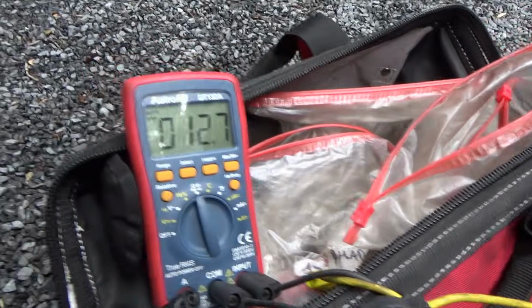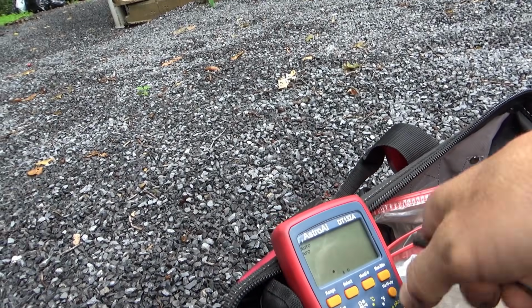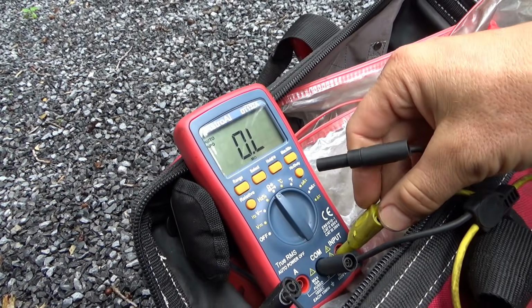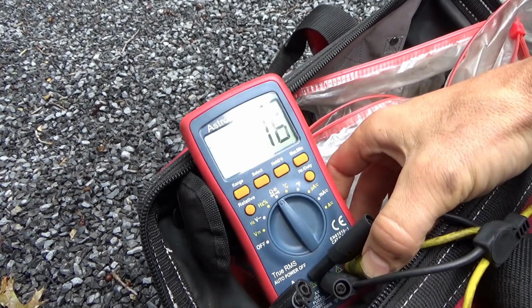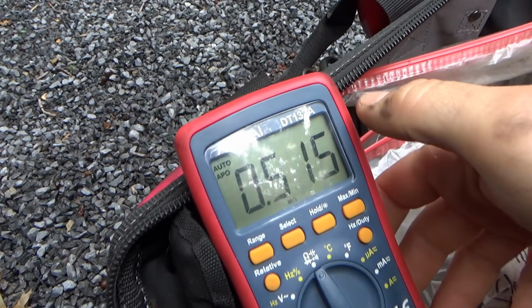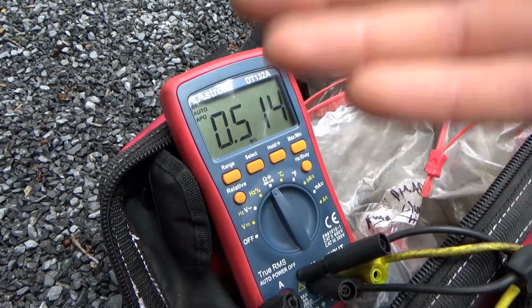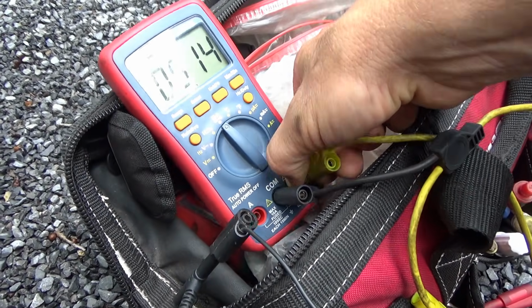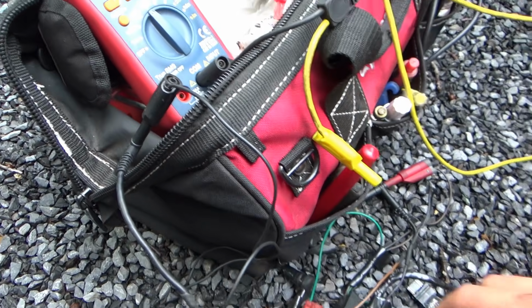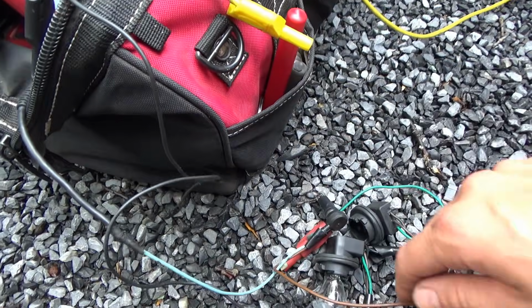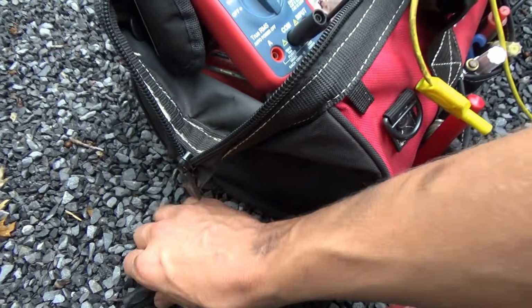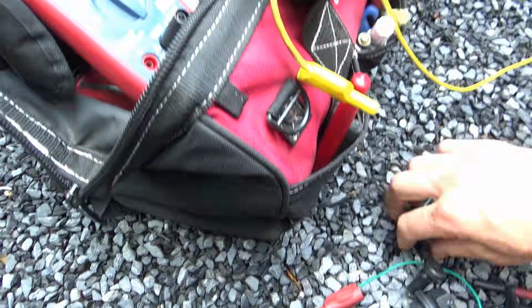We could also measure the resistance just to see if there's no short circuit on that leg from the control wire to ground, and it's 0.5 megaohms, so it's not rubbed through somewhere, it's not shorting to ground. That's a quick check we can do. So now I have a collection of test lights, and here's my little 300 milliamp. So how do we want to hook this up?